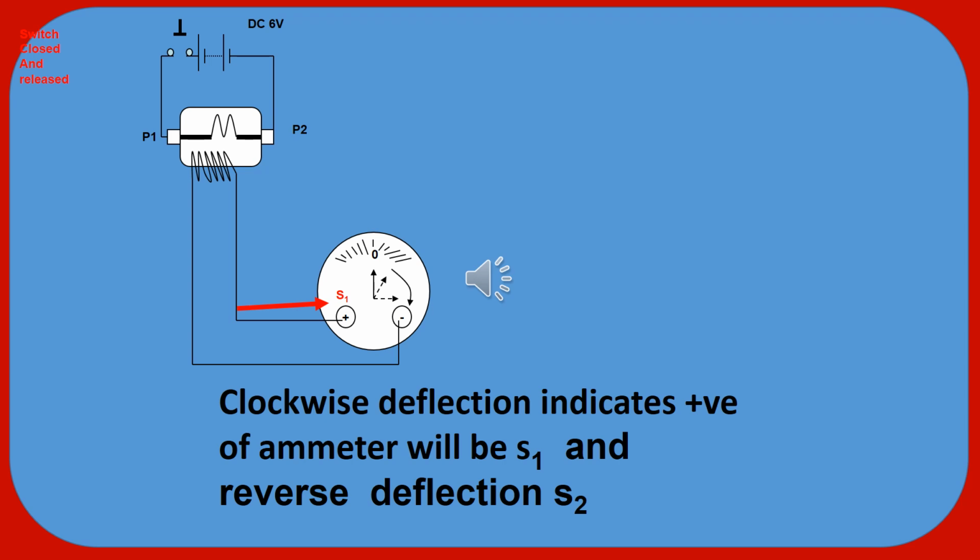I think you can easily find it out. The importance of this system is the connection in the electromechanical relay, especially. After that, I have already told you about the microprocessor relay, they have already programmed it. You have to fix the particular S1, S2 terminals. If you make a mistake, then the microprocessor relay will also show maloperation.